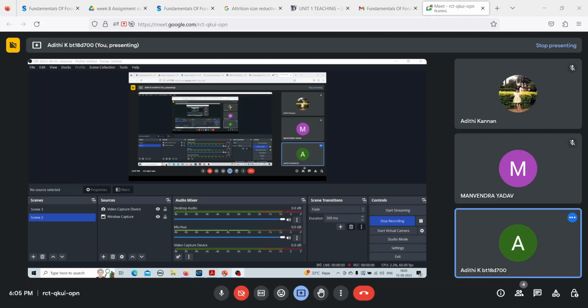In Rittinger's law, which we saw before, it applies for fine grinding where energy is proportional to the surface area. Since it is proportional to the surface area, we are looking at x square here. So m is equal to 2. In case of Kick's law, which is applicable for coarse grinding, energy is proportional to the linear dimension or size reduction ratio. So it is only proportional to the length of the particle and not any area or volume. So for Kick's law, m is equal to 1 here, and that is applicable in the case of coarse grinding.